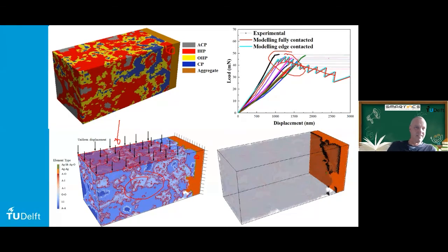Is there a specific modeling software you recommend using, like Abaqus or Risa? Yeah, that depends on what you want to model. If you want to model with finite elements on a somewhat larger scale, then there are several softwares that you can apply, Abaqus or ANSYS or Diana, which simulate fracture. They all have fracture models in their tools, so you can use them. And you can also model diffusion with them and couple that, diffusion and fracture. Which one is the best for concrete? I don't know on that scale. I don't dare to say that.